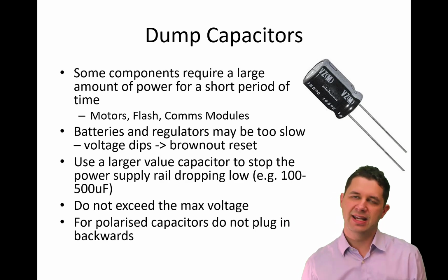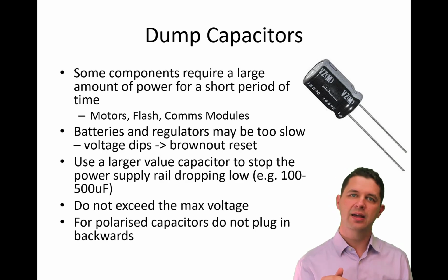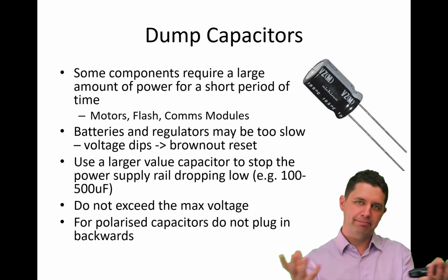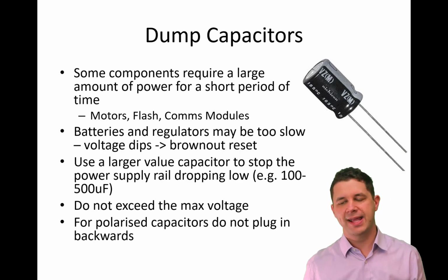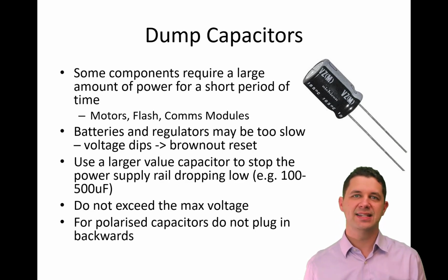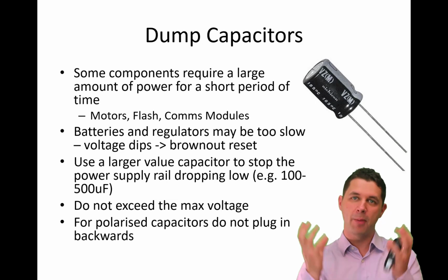Now, things we need to consider with these, we of course don't want to exceed the maximum voltage for the capacitor because they can blow up. We don't want to put them in back to front because they can blow up. And back when I worked at NEC, one of the standard tests that were done, whenever you turn on the board for the first time that was a prototype, you'd wear safety glasses just in case they did blow up and pop out of the board.